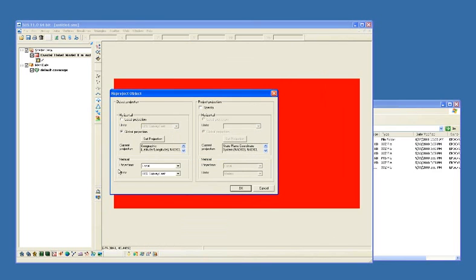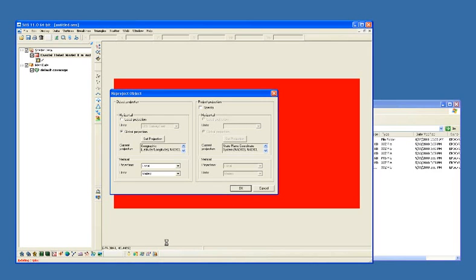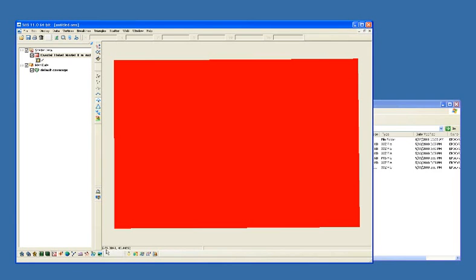Click OK, and then the vertical we're not going to change, so we leave it identical to what's on the right hand side, which is meters. You click OK, and instead of being in -74 degrees, it's now changed that, and you see that these values have changed now to a meters based instead of a degrees based unit. I hope that answered your question.